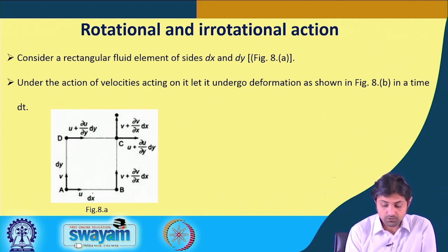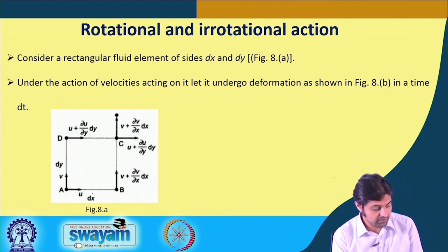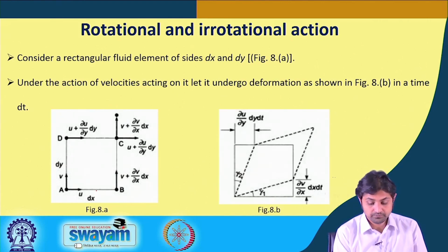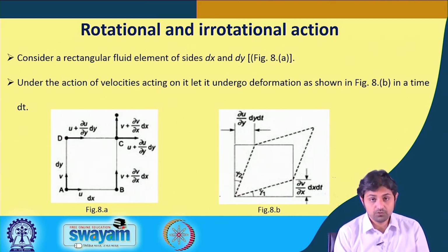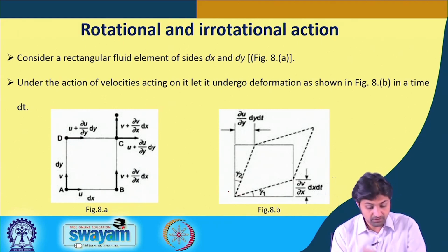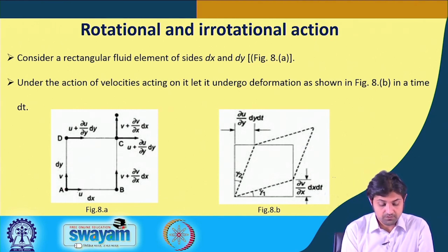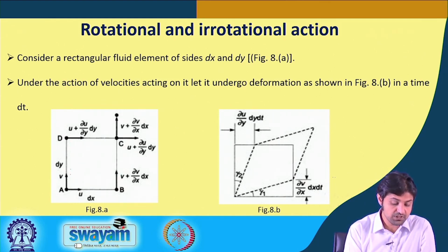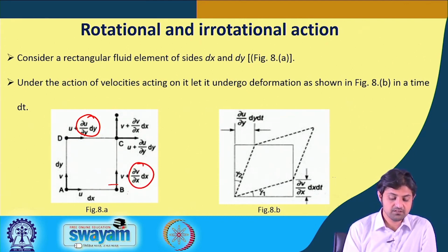This fluid element can undergo a rotation or a deformation, as we can see here. At point B the velocities are changing. u is changing in this direction as del u by del y into dy, and similarly this velocity is changing in the x direction as del v by del x dx.